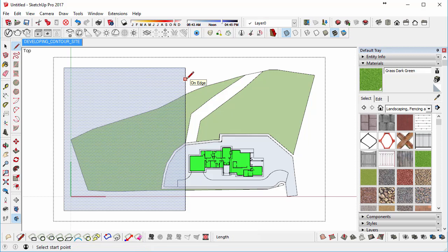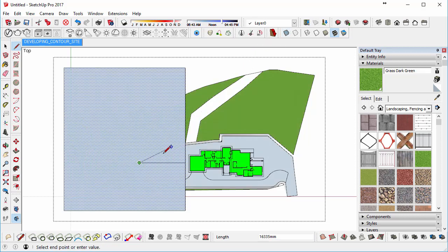I want to make sure that I'm drawing on this rectangle, so I'm going to hold shift on the edge with the line tool, and then click about there, making sure I'm on axis, so I'm drawing along the axis. Then I might turn off X-ray mode, go to the 2-point arc tool, draw a little bit of a curve, and then take that line out to the edge.